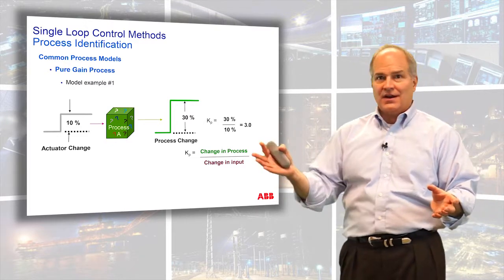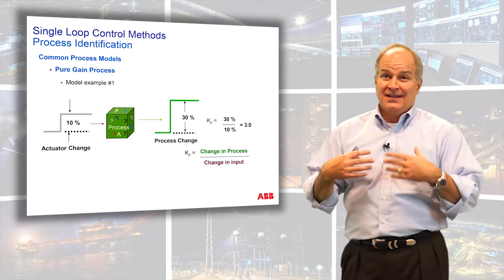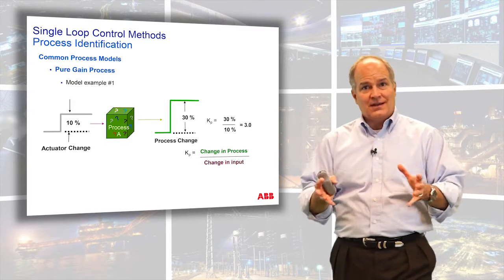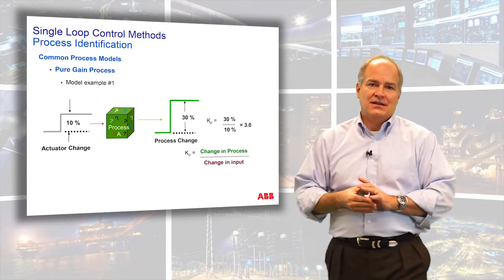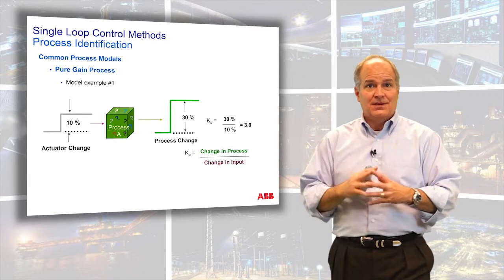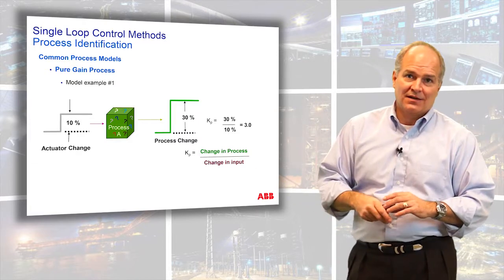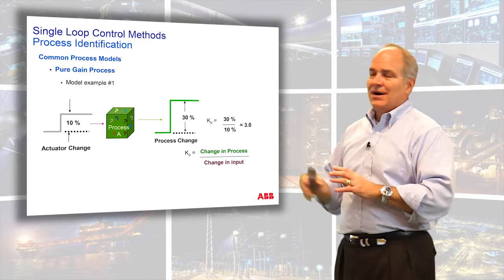Think garden hose, fire hose: how much do I move the process for a given change in the actuator? If you don't know that, your controller will never figure it out. So you have to figure that out. And another thing that you'll see, and we'll get into nonlinearities, is the valve curve. Where should your valve be during your bump test? There's the 30-60-10-90 rule, which we'll talk about in nonlinearities. But if your valve is in the 50 to 70% range, it's probably pretty reliable.